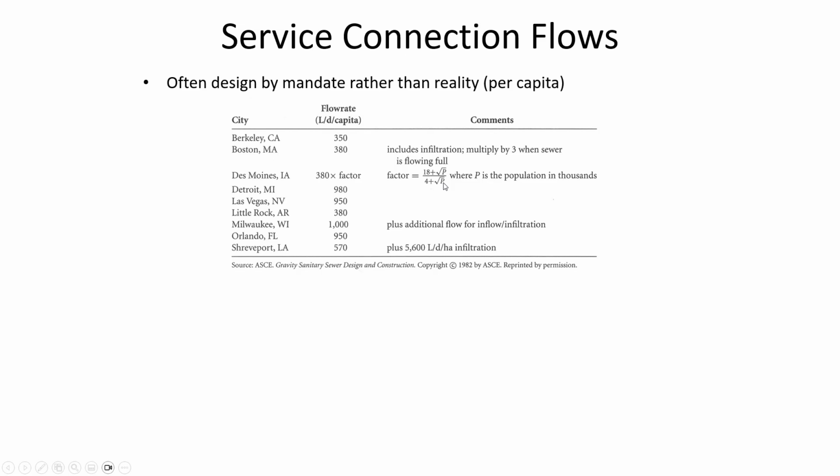The reason why population would be a factor that you'd account for is that if you have a really big population upstream, then it's more likely that they're not all going to be using water at the same time. In small communities, people tend to have the same working schedules because there's not as big a variety of employers.